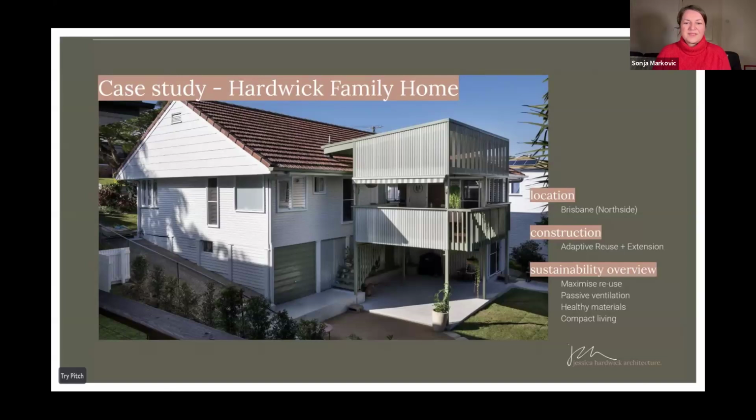Awesome. And would you recommend that void in the wall profile for anyone thinking of building in a subtropical zone? Is that something easy to incorporate? Yeah, for sure. It's very easy to incorporate. And the building wrap side of things is an element of construction that I think builders are becoming more and more interested in understanding, because condensation in buildings does create warranty issues.